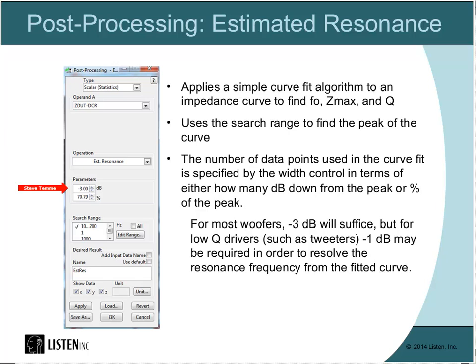And in general, you always want to have the start and the stop of the curve fit be on the point of the curve that's steepest. In other words, you don't want to curve fit when the curve's flattening out because you'll actually have more noise in that portion of the curve. Where if it's steep, the difference between two frequency points will have less effective noise. So keep that in mind when you're using this algorithm.